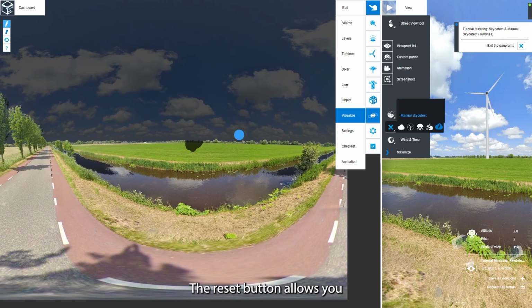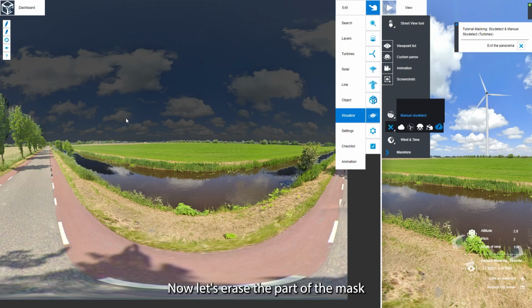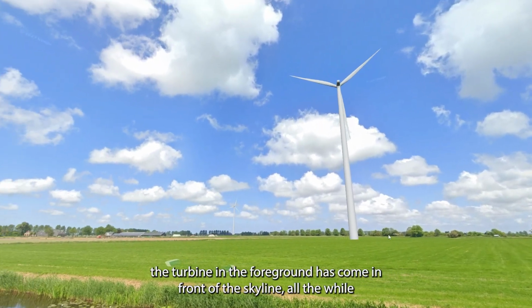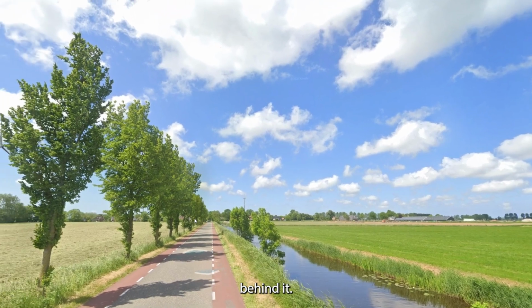The Reset button allows you to go back to the starting point of this mask, which is the Sky Detect mask. Now, let's erase the part of the mask where the turbine stands on the ground. As you can see, it now appears in front of the row of trees. Notice how using this method, the turbine in the foreground has come in front of the skyline, all the while keeping turbines that should come after the horizon or groups of trees behind it.